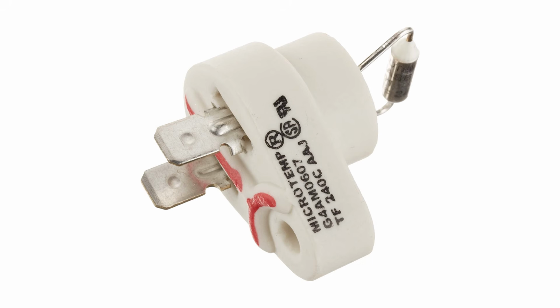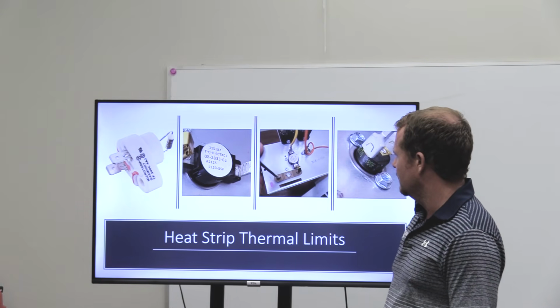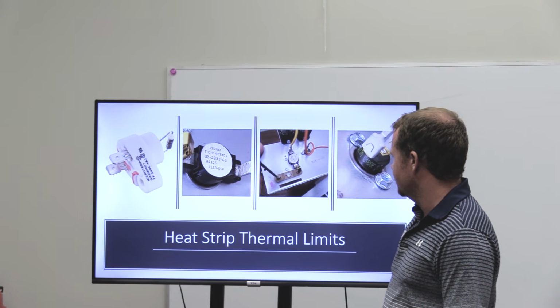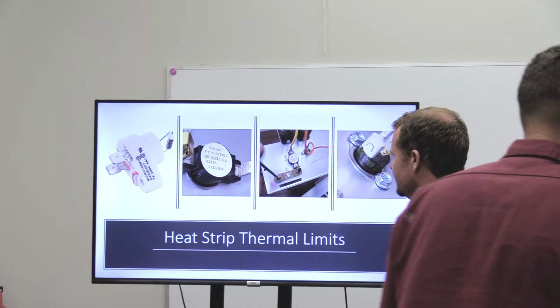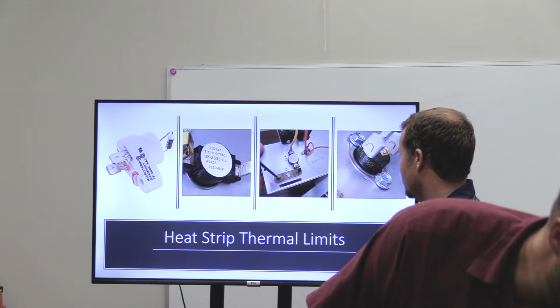A couple different types here. We've got a fusible link, which I wanted to mention quickly because you will see these sometimes. This is a single fail. So is the one with the orange wires. This one here is a thermal overload? Yeah, that's what Eric told me. He says he's pretty sure it's a single fail. I don't think so. There's a button right in the middle of it, you can click it. Reset it, but if there's not, then it's a single fail. I still think it's auto reset, but whatever.